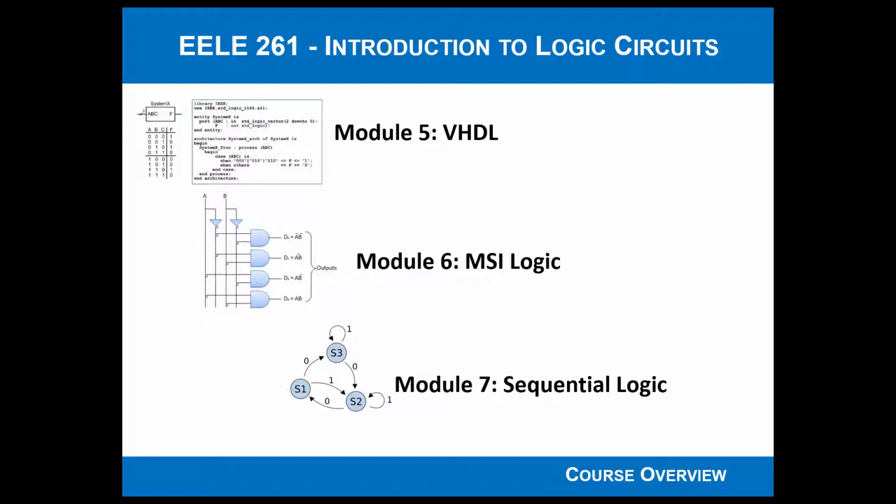We will learn about one particular language called VHDL, and this is where we actually type out a description of the logic circuit that we want, and then since we're typing it out into a computer, we can actually perform simulations on our description to make sure it's what we wanted, and then we can actually allow the tool to synthesize basically a schematic that we can then download onto a programmable logic device. And so you'll get experience with the modern digital design flow where we describe these combinational logic circuits, and then we allow the tool to actually create the circuit for us, and then we can test it using a programmable logic device that we hook to our breadboard.